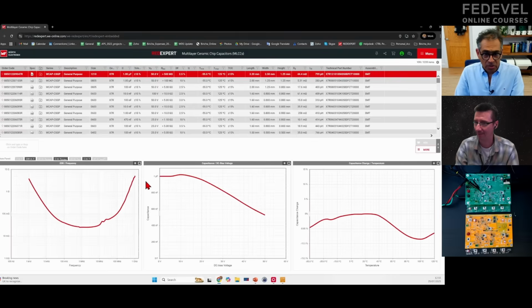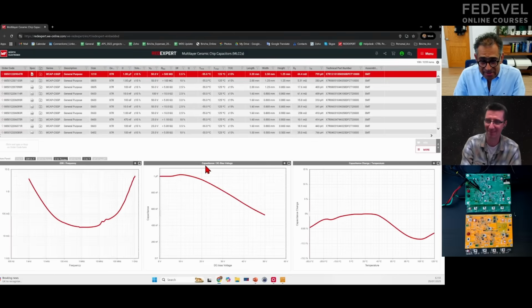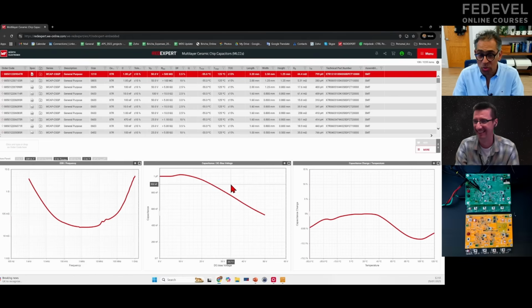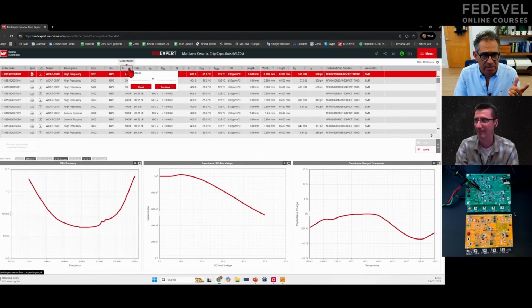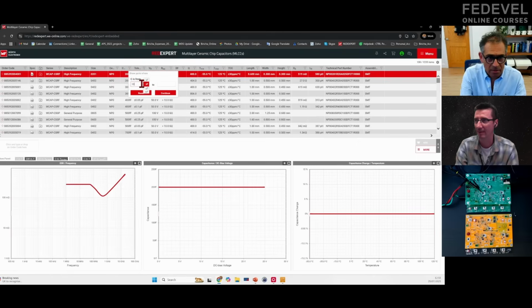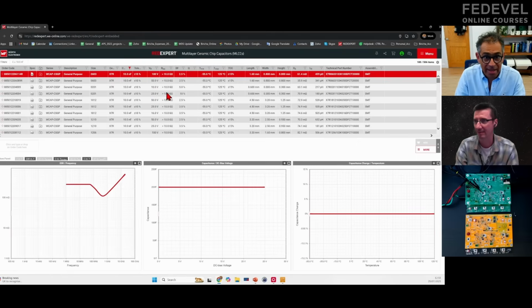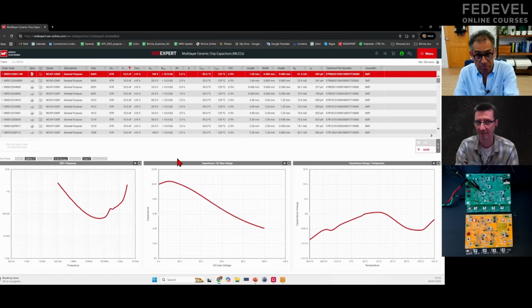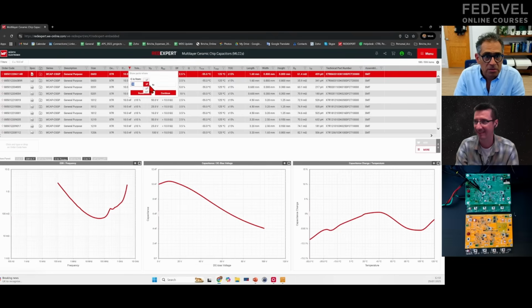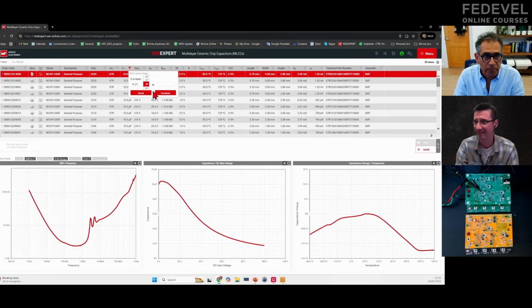Okay. Oh, so, I can see DC bias. Versus DC bias, right? And this is normal. All capacitors, all big microfarad ceramics are like this. Now, if I remember, it was 10 microfarad, wasn't it? What we calculated? Let's do 10 microfarad. And the higher the microfarad, the worse this is, right? So 10, it's this 10 nano. Let's do 10 micro. Look at that.